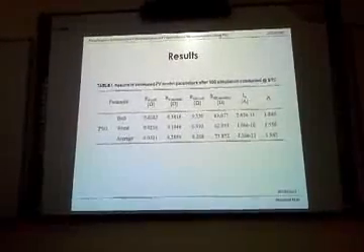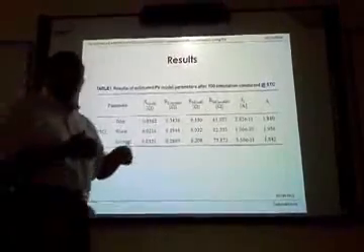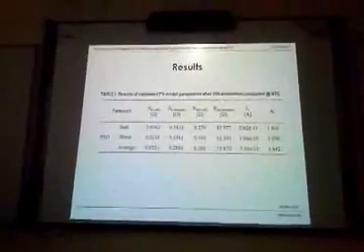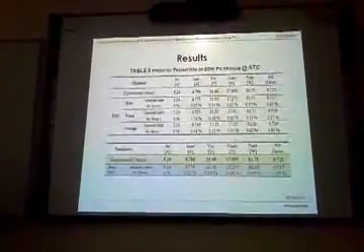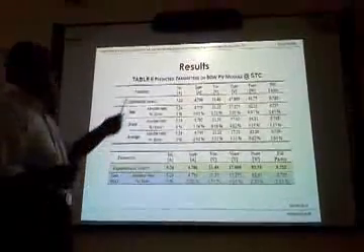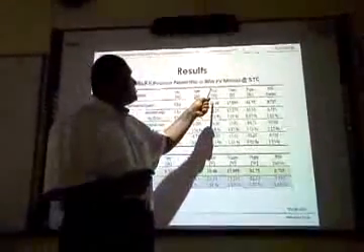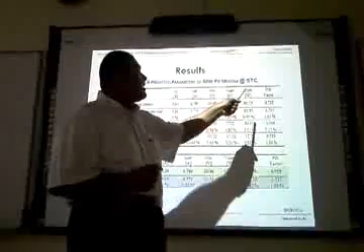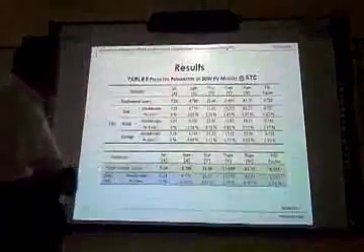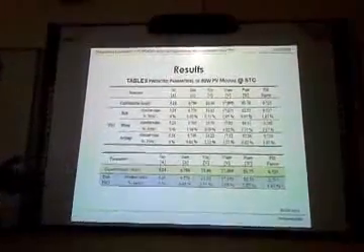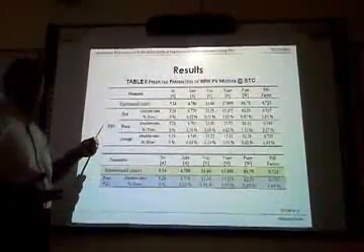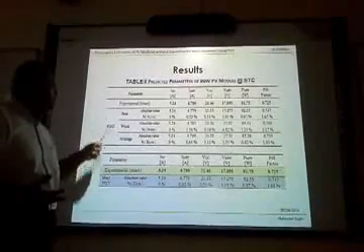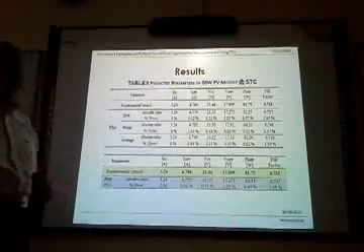From these values, we compute, or we predict, short circuit current, maximum power point current, open circuit voltage, voltage at maximum power point, and power at maximum power point, and the fill factor value. We computed these parameters for the best obtained PSO parameters, worst obtained PSO parameters, and for the average value obtained after running the system 100 times.